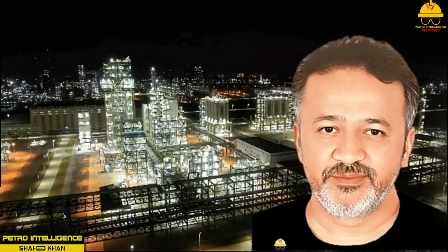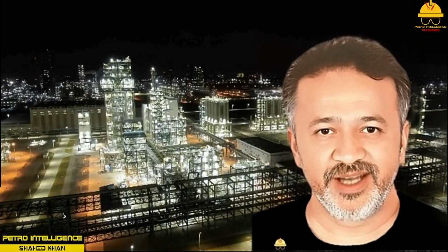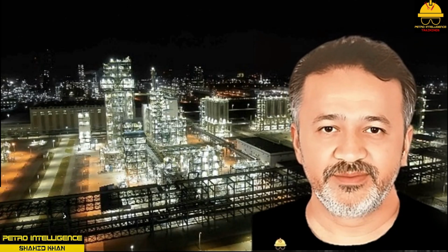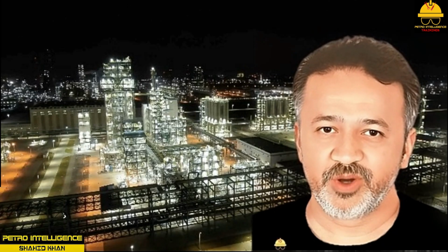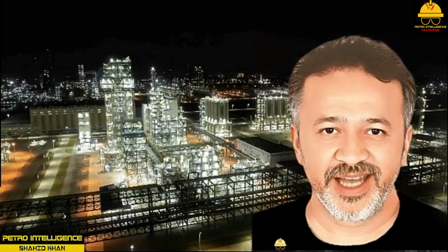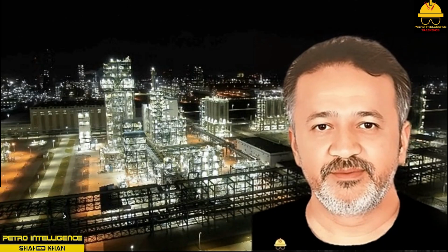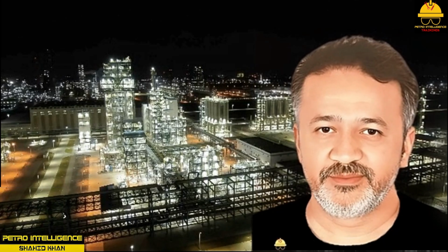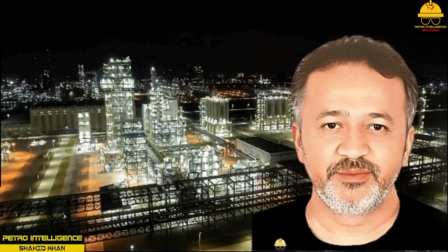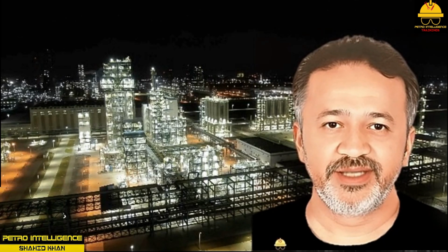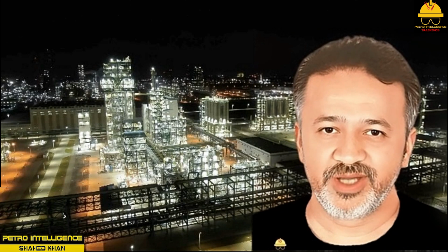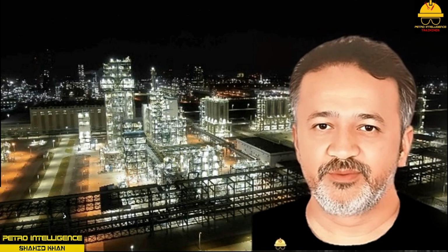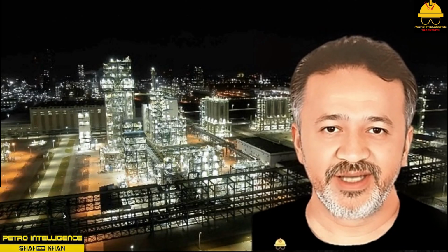Pressure symbols. The most common pressure devices are pressure gauges, manometers, and pressure transmitters. Pressure gauges are represented on a P&ID as PI, or pressure indicator. A circle with PE is the symbol for a pressure element. A diaphragm in a DP cell is an example of a PE. A simple equation can be used to determine pressure: P, pressure, equals F, force, divided by A, area.